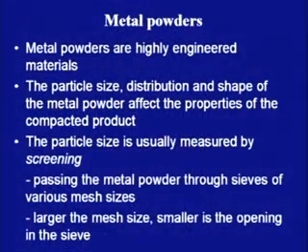Then coming on to the particle size. The particle size is usually measured by screening. Now, what is this screening process? Anybody who has some idea regarding casting, sand casting in particular: in sand casting we make use of sand. The sand grains have a certain fineness, so we calculate a grain fineness number. There are different sieves through which the sand is passed and we calculate the grain fineness number. Similarly, metal powders also have a size, the size of the particle, and this is found out using a very simple technique, that is screening.